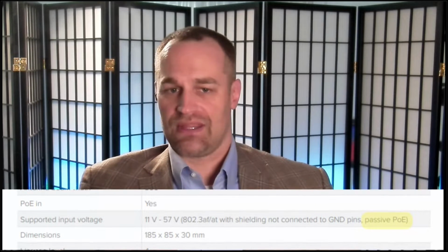Now, every now and then, a company does manufacture a 48 volt PoE device that only works on mode A or mode B. They're relatively rare, and it's contrary to the PoE standards set by the Institute of Electrical and Electronics Engineers, aka IEEE. But it turns out that they don't have the power to arrest people for violating their standards. So occasionally somebody will still do it. At any rate, it's easy to solve this problem by simply switching to the other mode.